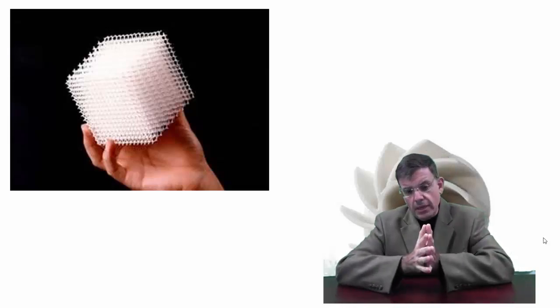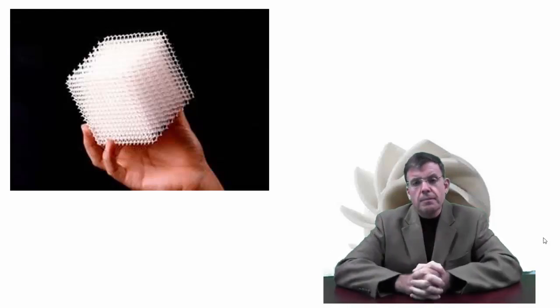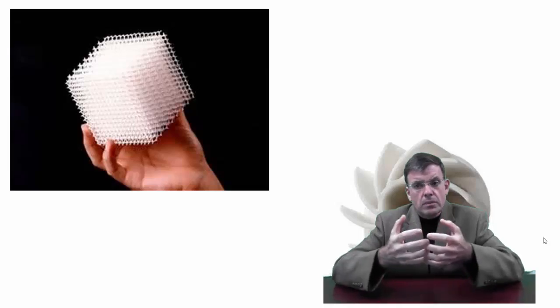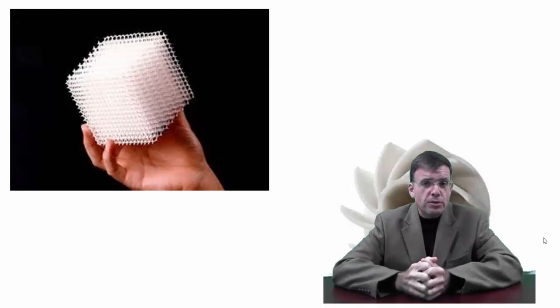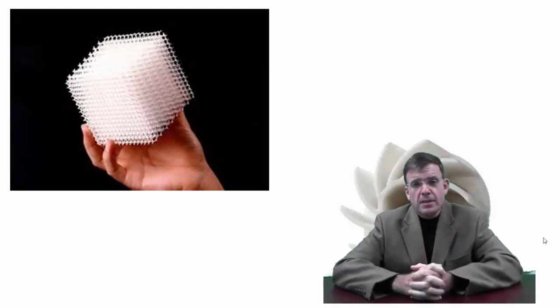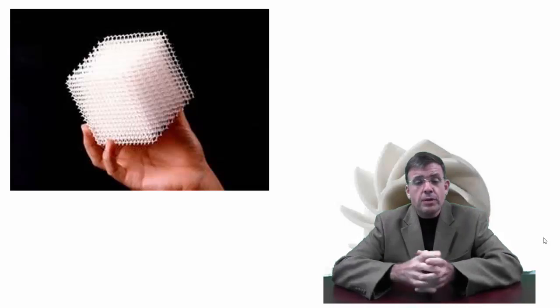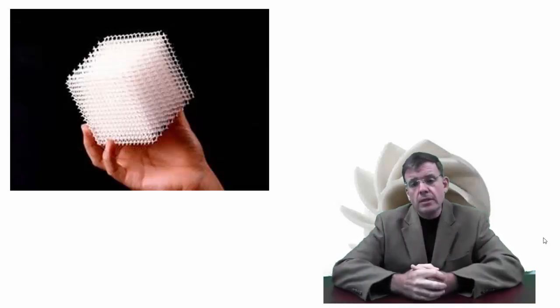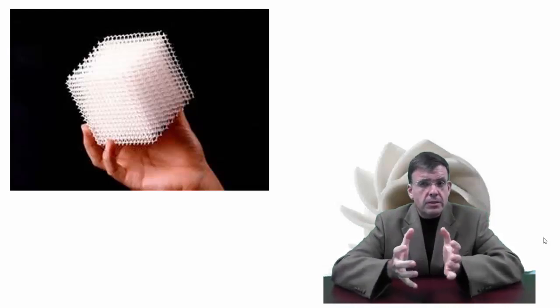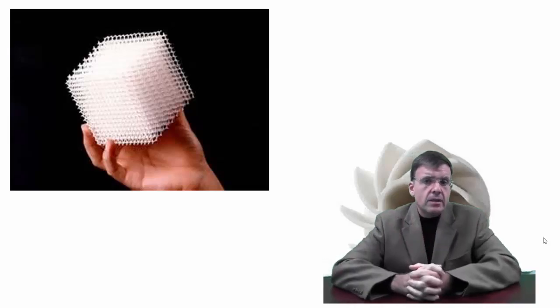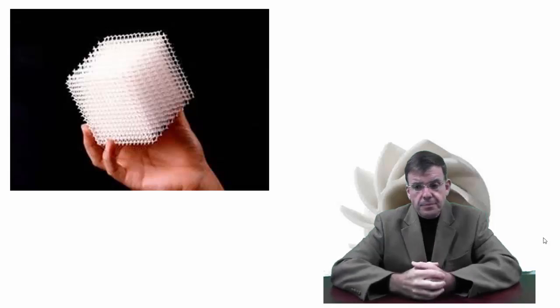So this is an increasingly useful technology. In fact, more than that, it's actually quite approachable these days. You can buy your own rapid prototyping printers, most of them based on the fused deposition modeling or the extrusion process, which tends to be not necessarily the highest resolution, but certainly good for many parts, and using real materials such as ABS and others, nylon even.